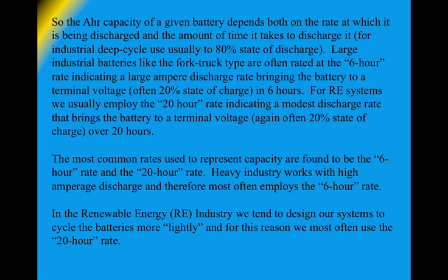Now this works in your typical industrial facility because the battery is going to be charged up, not unlike your automotive battery, overnight. They're going to use a large battery charger tied to the utility grid and charge the devil out of that battery, bringing its capacity back up to full, and the battery won't have time to degrade and sulfate as a battery that was sitting in an 80% state of discharge for an extended period of time.